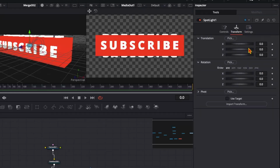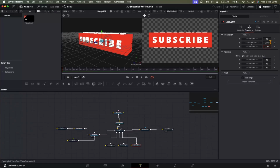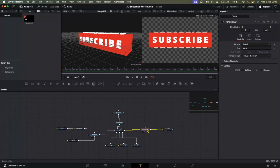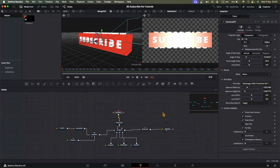Now lastly, go to the transform tab of the spotlight. Change the Y position to minus 0.033, the Z translation to 2.87. So go to the render 3D node and from the software renderer, change it to hardware renderer and enable lighting and shadows. Now go to the camera 3D node and now we have to do some animations.